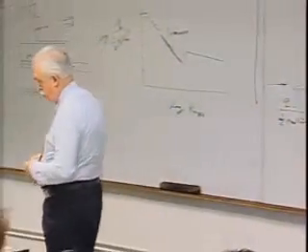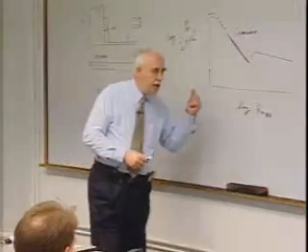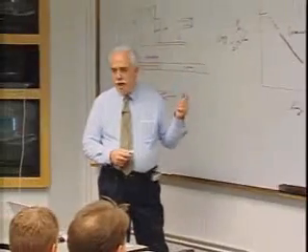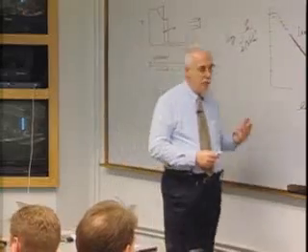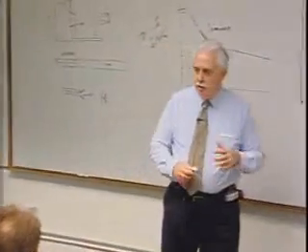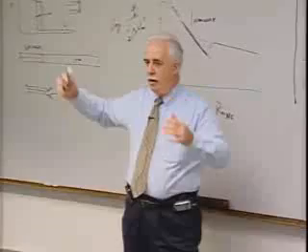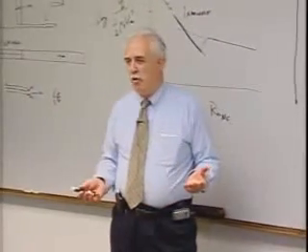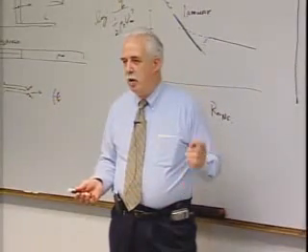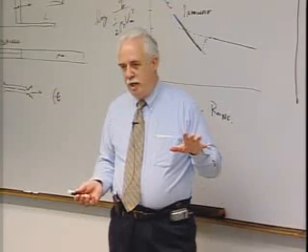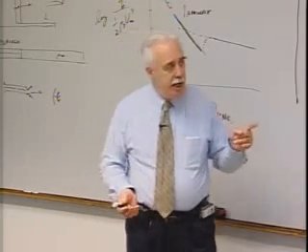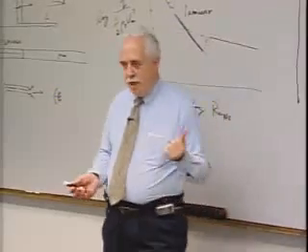What we learned was energy is extremely important, the enthalpy. And frankly, going beyond Mach 8, which is what everybody tried to do, get to a higher and higher Mach number, really doesn't work too well in a ground facility when you're talking about heating distribution. It does give you Mach number effects, okay? But the gas is not at all like what you have in flight.